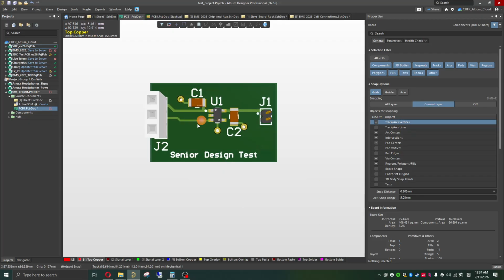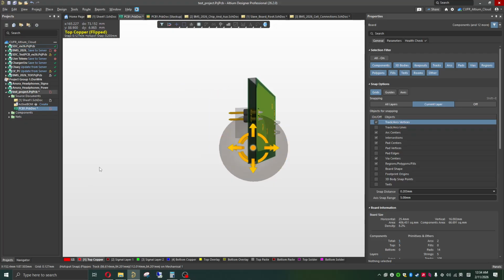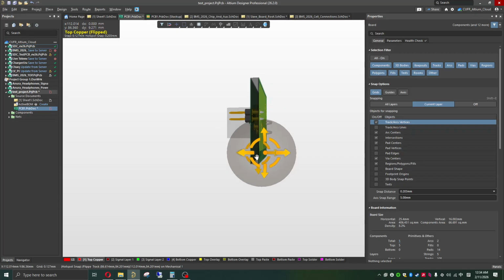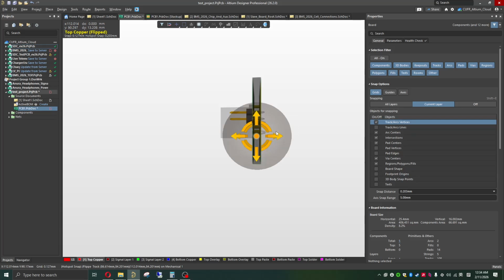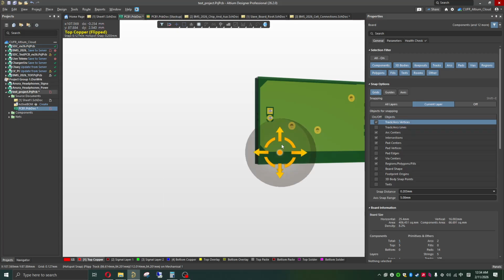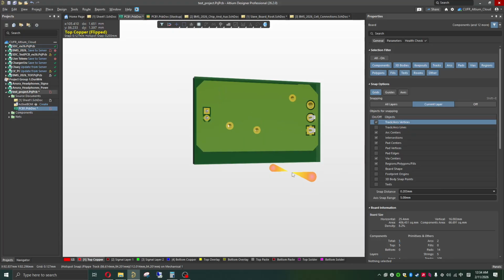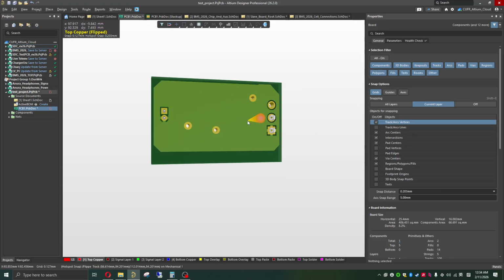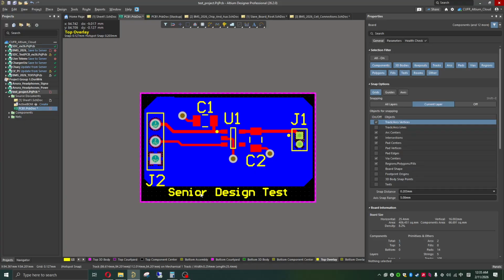So you see this is where I've made all the holes for my vias. And you can see how with the stack up that I've created, it shows you the definitions of your different holes and your different via connections. Pretty neat. Right. You can see the copper plane as well, and how we've defined the different copper layer definitions from before. So going back to the 2D view, we have a pretty set circuit.